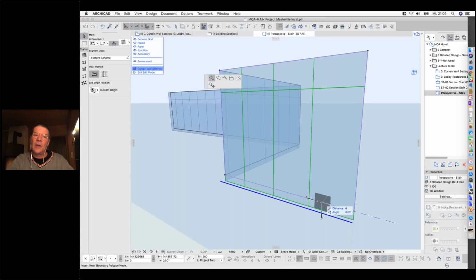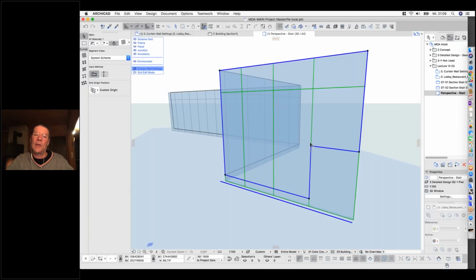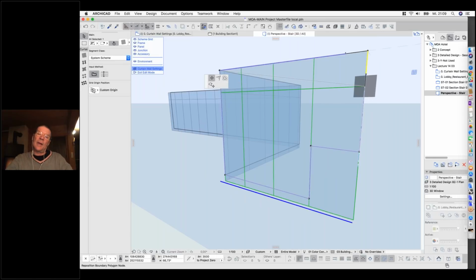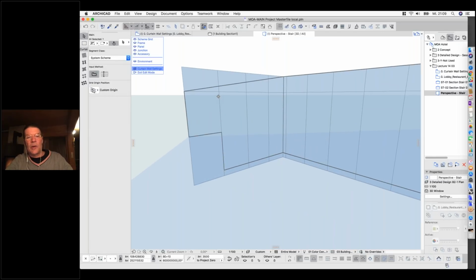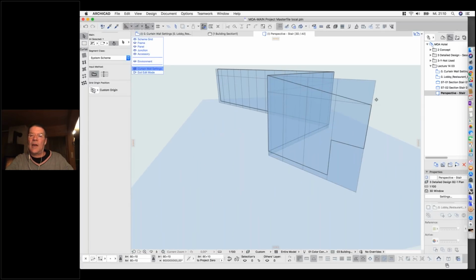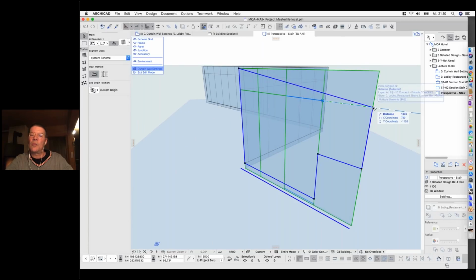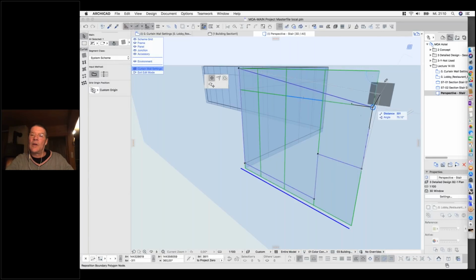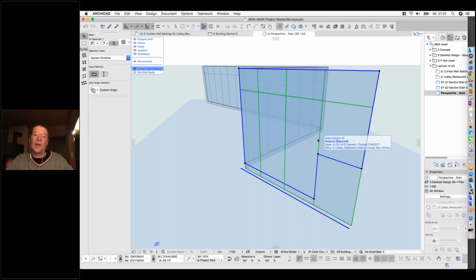But when you want to change it, you can do almost everything what you can do with a boundary. You can add nodes, you can move edges, and whenever you have done that, you have to be aware, and you can round them. Okay, let me play a little bit. You can move just one node, and so you are pretty flexible in generating within your grid scheme any of the boundaries. So the secret is just you have to be aware what you are touching. Are you touching one of the grid lines, or are you touching a node of the boundary? And you can see it can get very tricky. Sometimes it's necessary to move around the 3D window just to find the node. But once you have found it, it's easy to change it.